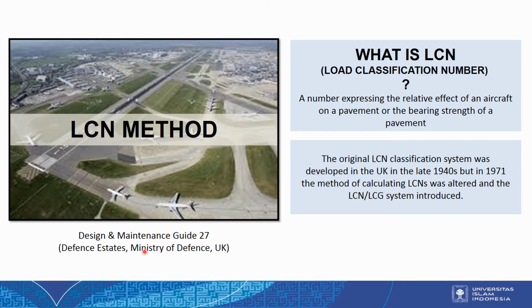So what is LCN, or load classification number? LCN is a number expressing the relative effect of an aircraft on a pavement, or the bearing strength of a pavement. So basically LCN is not a design method, but it is like the PCN. It just expresses the relative effect of an aircraft on a pavement, or we can say the bearing strength of a pavement. So LCN is not a design method.